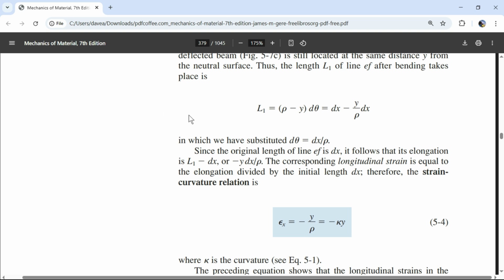So the change in length compared to the original length is important. That gives you the percent change. That's why if you say steel has a percent change in length of 0.2, it doesn't matter if it's the Golden Gate Bridge or a climbing carabiner. No little segment on that steel can lengthen more than 0.2%.